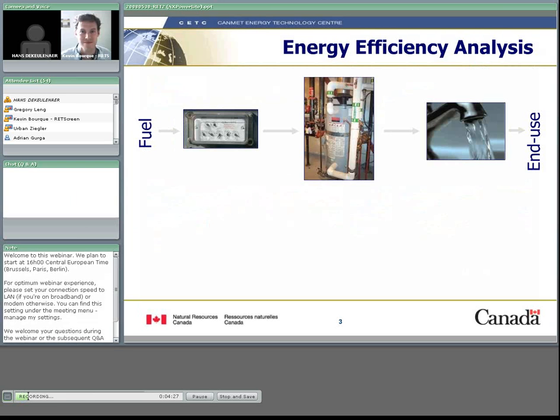In this case, on the left-hand side, we have a meter, a gas meter, I think. RETScreen considers electricity as one of the fuels. One of the reasons is we need to do a proper energy balance. And if you consider what is the fuel that powers, say, your lighting or your computer screen, it is electricity. Now that electricity is generated somehow, it may be just from the grid, and we can evaluate the fuels that do that. But in RETScreen, we do have electricity as a fuel, and that way you won't forget it as well.